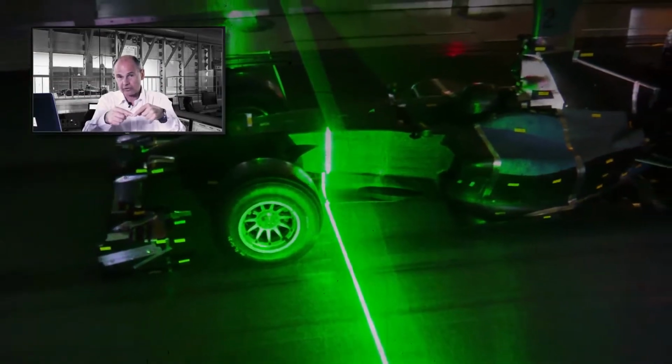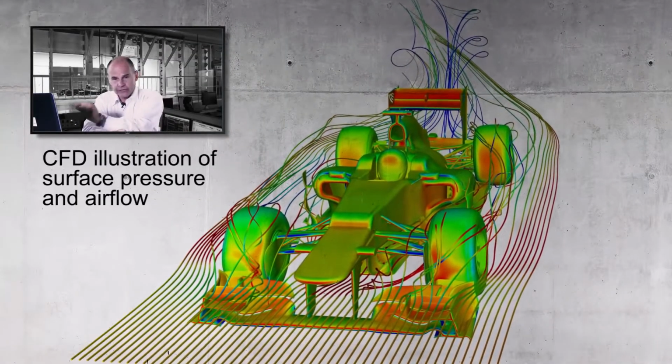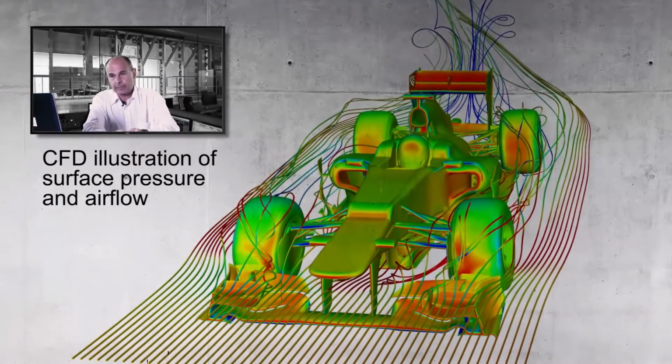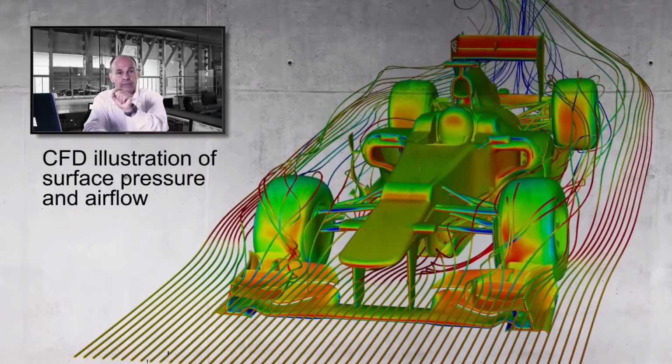There are also systems such as laser measurement systems for air movement. They don't actually detect air movement. It's basically laser light, either in a sheet or a few lasers pointing at a single point. You need something visible to use the laser to tell you what's happening with the airflow, but a smoke particle is more than enough to be visible. And as the visible particle moves through a tiny space that's lit up by a special laser light, we can use that to detect the velocity of the air, so the speed and direction, and also the turbulence level of the air. So these are technologies that we don't talk about very much, but these are technologies that exist and we have available for our wind tunnel and we use for our wind tunnel.